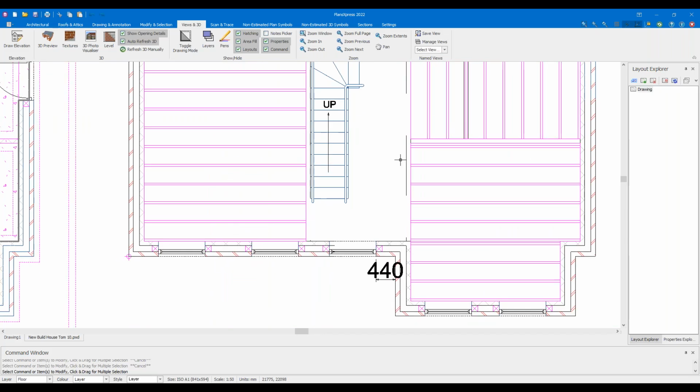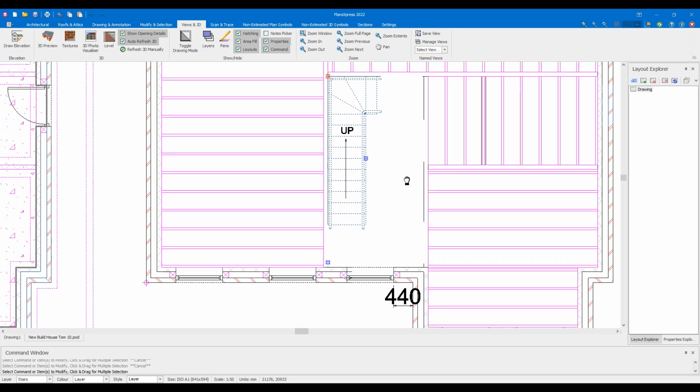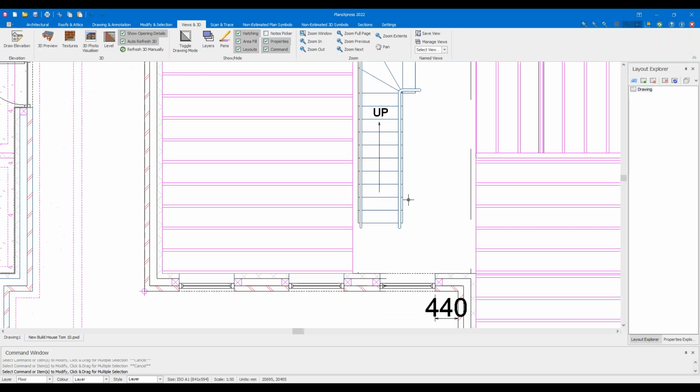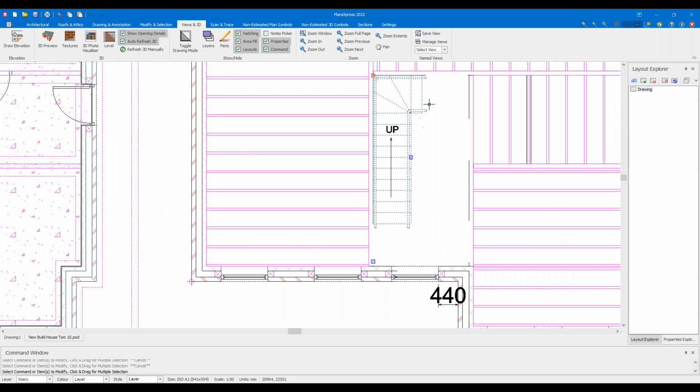Now, before I draw in the floor for this section, I need to return back to these stairs. Because I've made a boo-boo, I've not done these yet. But I've left them till now so you can see what we need to consider. The floor here is going to go in just here. Now, if I leave this as it is, it's going to be a bit too narrow before we get a door in here, especially for any railing going across the top, some banister. So what we need to do is reduce the length of these stairs, because these are not the actual stairs. These are just the lines we require to be able to see the size of the stairwell.